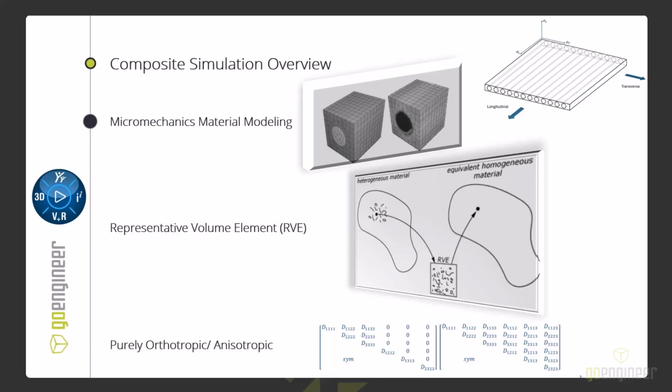demonstration today. And then for those among you who are a glutton for punishment, let's say, you can also define these material properties explicitly by actually inputting the orthotropic or anisotropic stiffness values directly into a structural matrix environment. This is a very manual process, but if you happen to have these values from some sort of physical test or something like that, you can input them directly.